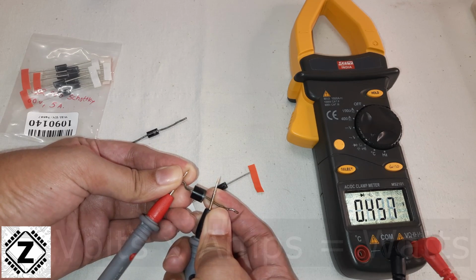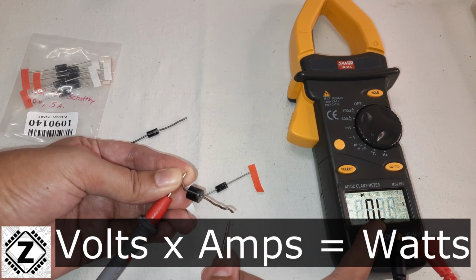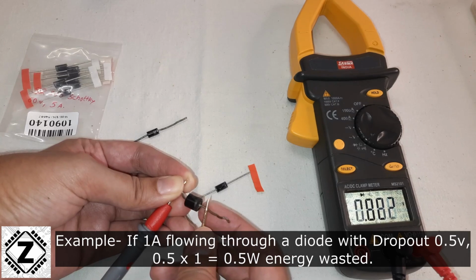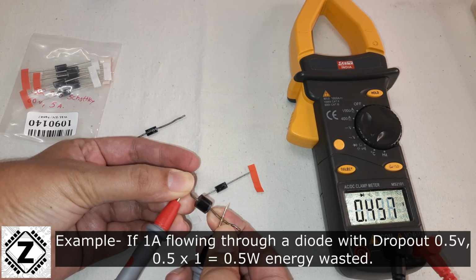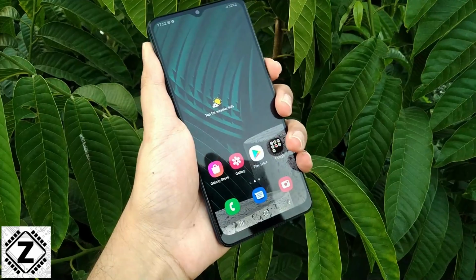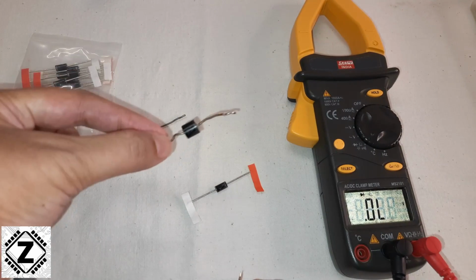And if we multiply these values, if we multiply 1 amp by the value on the multimeter, that is half a volt, we get the resultant energy loss in watts. That is, it's going to waste half a watt of energy as heat. And assuming that we need our devices to be as efficient and as light as possible, you don't want bulky heat sinks on them, this kind of wasteful property of a general purpose silicon diode is not very helpful.